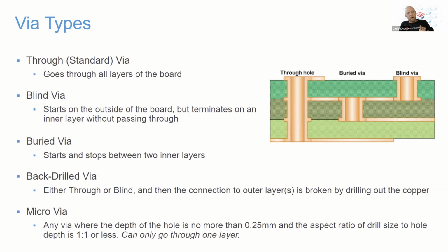Now, one thing you do typically want to avoid, and most fabricators will actually automatically correct this for you, is for your slots. There is an old way of doing it in the Gerbers, which is called a drill and drag, which is to say it would use a command to run the drill bit through or into the board and then drag it across to make the slot.